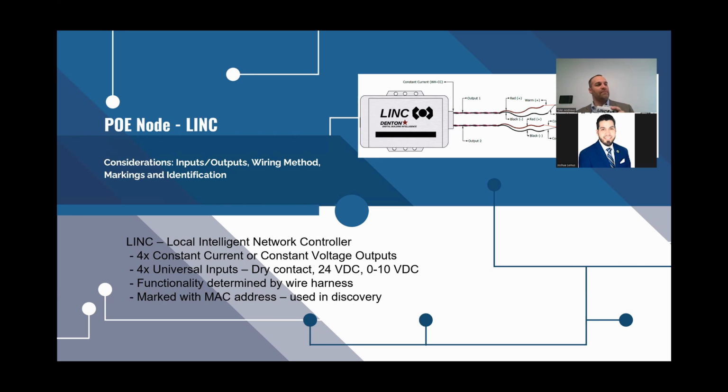You can choose a lighting manufacturer who will put the node in. Some lighting manufacturers and some PoE controls manufacturers will put the node in, whether they call it a node or not, or whether you have an RJ45 port on the back of the light, there would still be a node inside. Either way, you have some smarts that is doing something to control the lights. This guy ends up being a replacement for the AC to DC LED driver. And that's an important piece of knowledge.